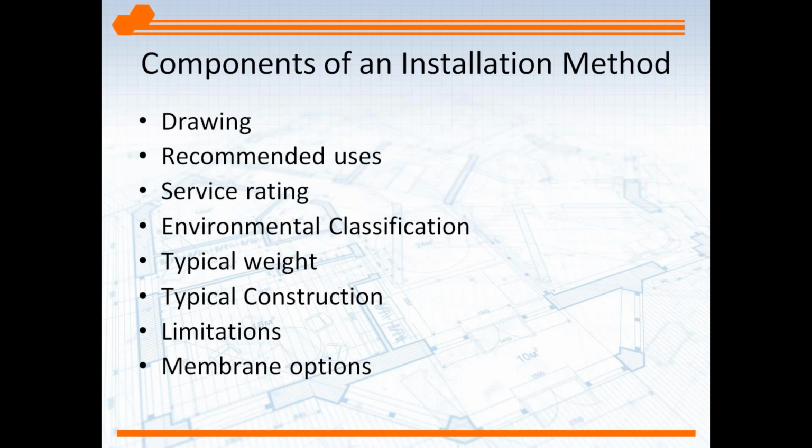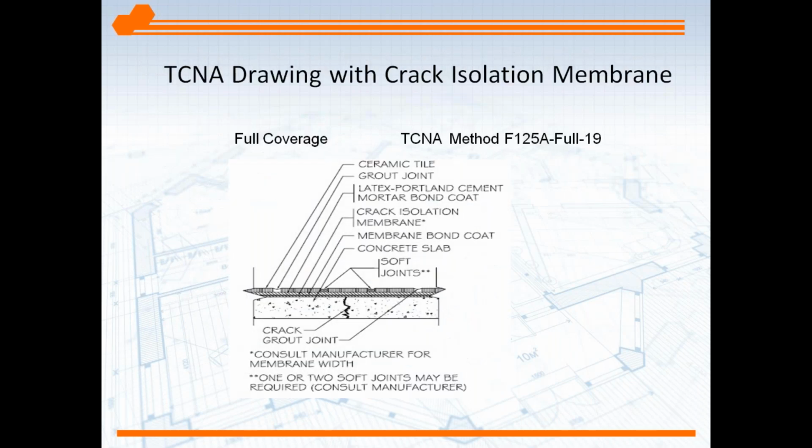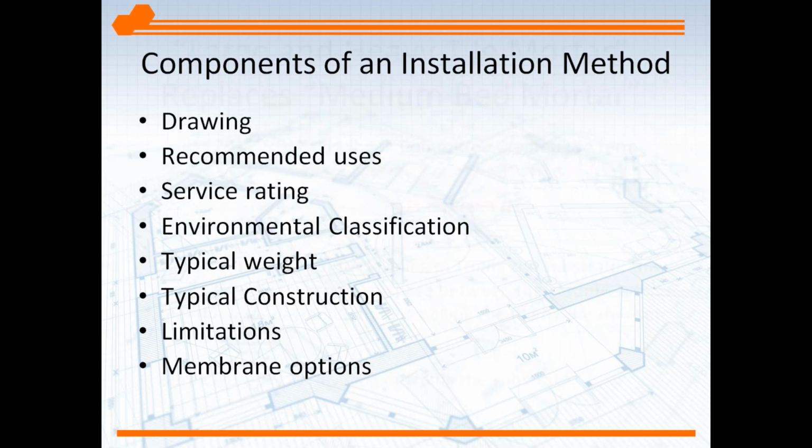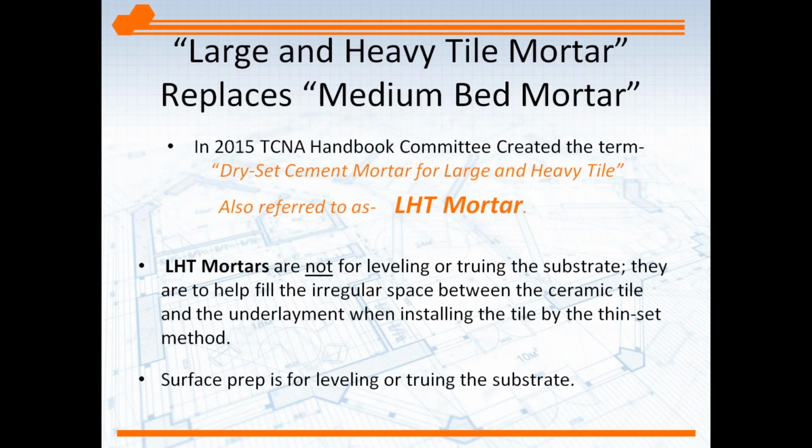Limitations, some things to be aware of when designing with this particular method. Some situations you don't want to walk into with this method, maybe you want to look at a different one. And of course, as I mentioned, the membrane options. So you'll have a drawing with the membrane option of a waterproofer or a crack isolation membrane. And these are the categories that come along with this picture in an installation method in the TCNA catalog. And of course, there's installations over concrete, over wood, pretty much everything that you can imagine. And we talk about the mortar.